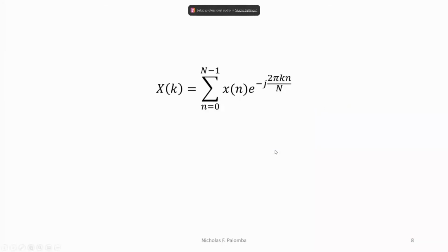So, as you all know, the discrete Fourier transform, or DFT, converts a finite sequence of equally spaced samples of a signal, x of n, into a same length sequence of equally spaced samples of the discrete time Fourier transform, or DTFT, x of k. Since it deals with a finite amount of data, it can be implemented in computers or other dedicated hardware. As such, it's probably the most important discrete transform in DSP, and I'm going to focus on it here.